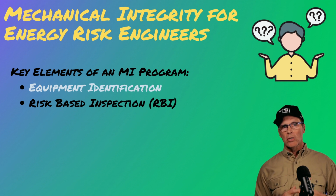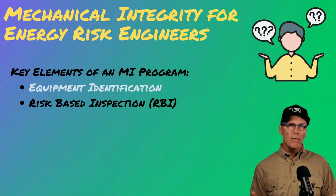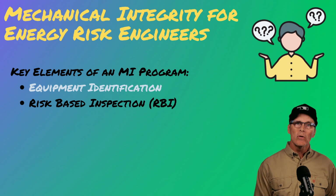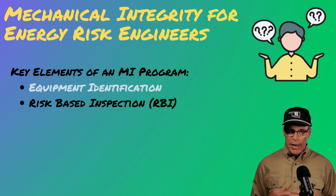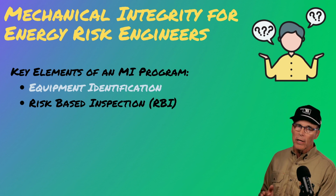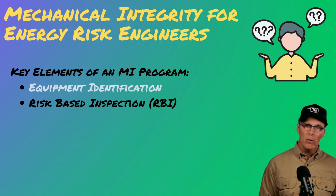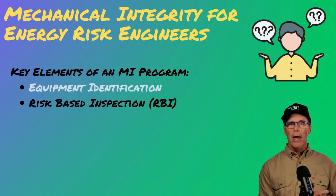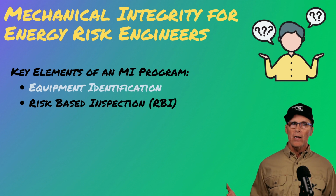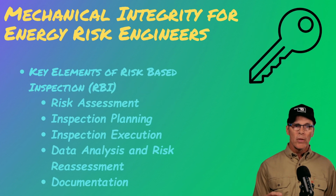Risk-based inspections, okay? What is a risk-based inspection? Well, we're going to look at equipment often enough to keep it from failing at a frequency that interrupts us or a frequency that's unacceptable. And that's what the risk part of it is about. In a compliance world, you're going to do it because the regulators say it has to be done once per year. You may find financially that it's more economical to do it 4 times per year. You're allowed to do that. It's up to you if you're doing a risk-based assessment. You may find that it's once every 5 years, but until you do the assessment, you don't know which way that frequency is going to go.